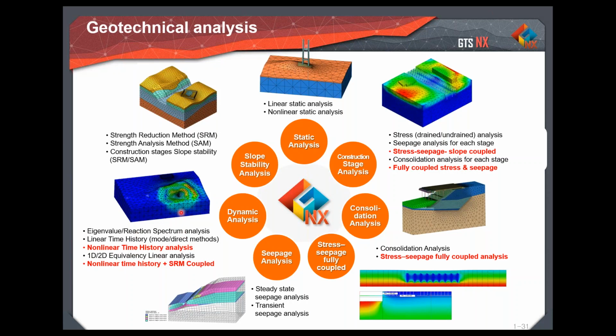Apart from this, we also have 1D ground response analysis. This 1D ground response analysis is very helpful in order to know the dynamic properties of your soil, and even that is present in the software. Once you provide the layered conditions and run the analysis, it will provide you with the damping ratio and the converged shear modulus. Once you get the dynamic properties, you can apply them to your general structures and go for time history analysis or response spectrum analysis. That's how strong GTS NX is in dynamic analysis.